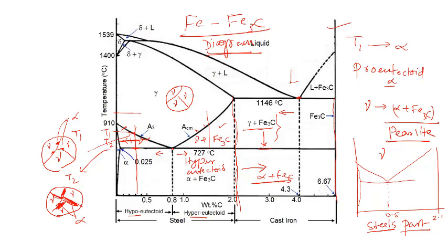And what is that phase of carbon or that state of carbon which will come in here? If carbon has to be present as free carbon, then in what form can it be present? Graphite. Okay. So the iron carbon diagram then basically belongs to the graphite phase and not really the cementite phase. In other words, you could say that cementite is not a very stable phase.